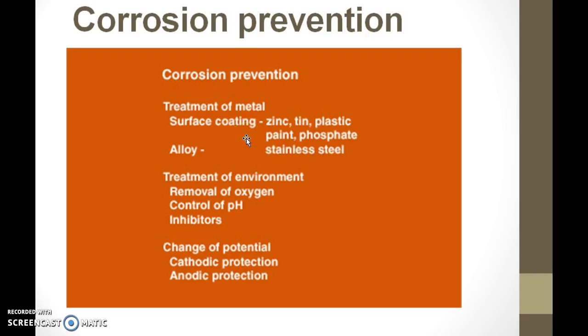There are different types of corrosion that happen. We can use many methods, such as treatment of the metal surface, coatings, cathodic protection, and anodic protection. We can use paints, organic coatings, and metallic coatings. These include phosphating and anodizing. These are some of the methods we are learning here.